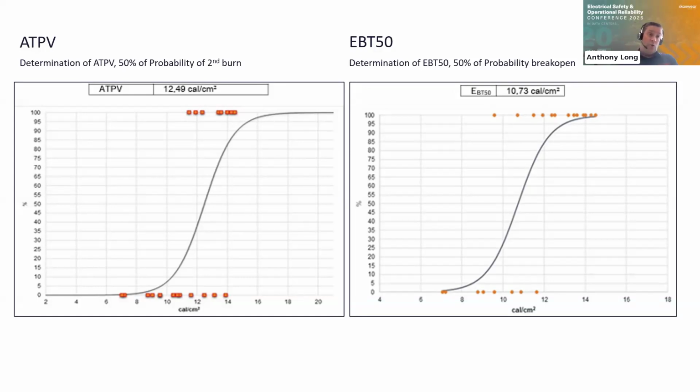So for everyone on the call, European ARC tests have to be done as a maximum every 5 years. ASTM tests are only ever repeated when there is a significant change. So if you've got an ASTM rating on a fabric and no European rating on a fabric, check when the rating was of that fabric, because it might be quite old and things will change. In the European test, it was redone again because obviously it was old.